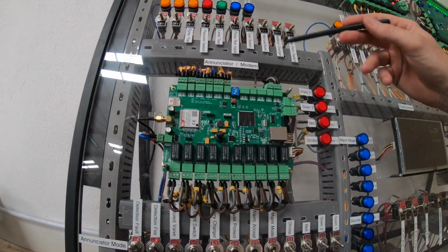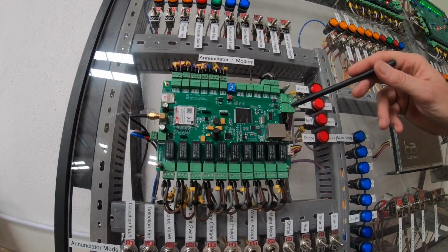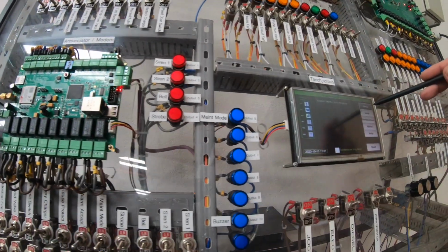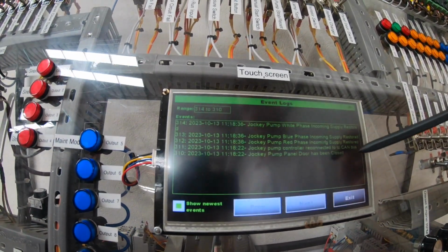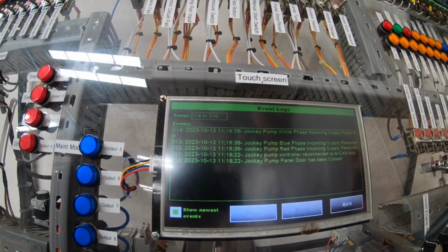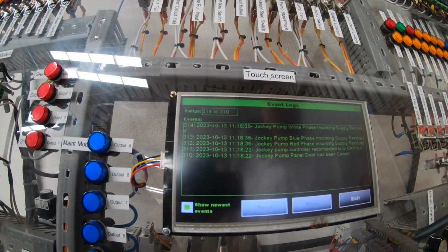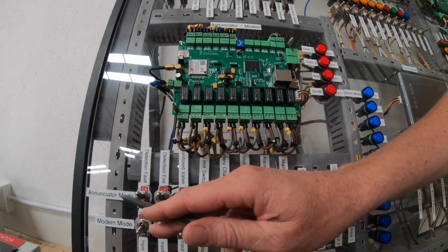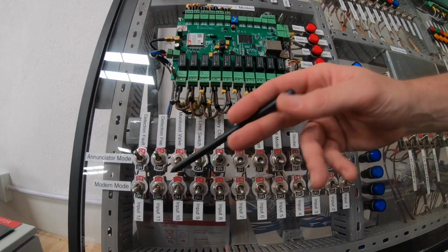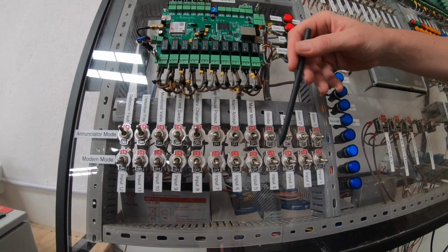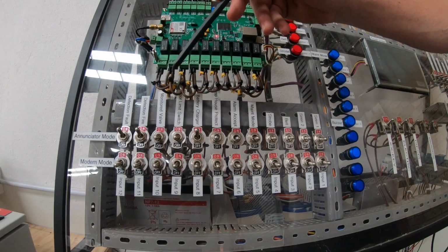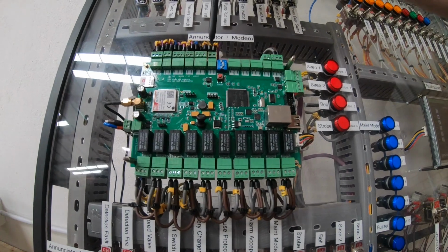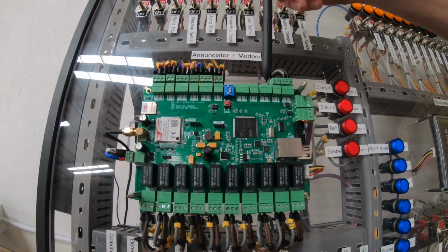Each of the controllers sends the information onto our CAN bus to this annunciator, where the annunciator logs the information onto the display, as well as all events, all conditions get recorded on the BuzzApex platform, where no events can be deleted. With regards to the annunciator, as explained earlier, we have 2 modes: the annunciator for the sprinklers and the modem for monitoring of fire detection systems or any HVAC, any equipment that you would like. On the annunciator, each input is registered to an output, or one input can have 4 outputs recorded and programmed.